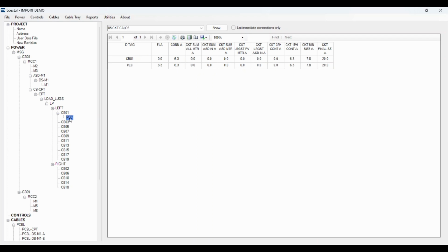So we're going to run L cables to the controls, but the controls that are inserted down here in the controls branch do not add to the load of the system. They are covered by the load that was all added right here. So now we have our anchor for our control system, and I'll show you why that's important in just a second. So we're going to go and import controls.